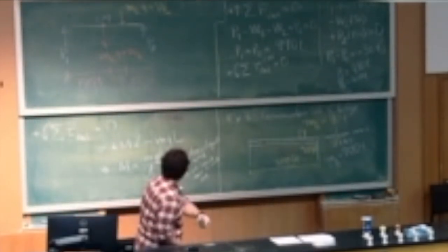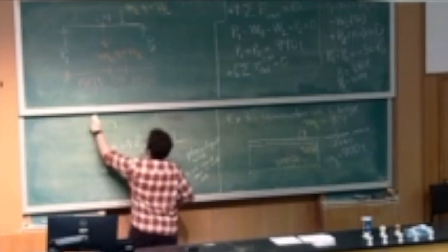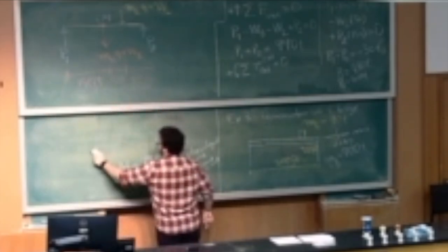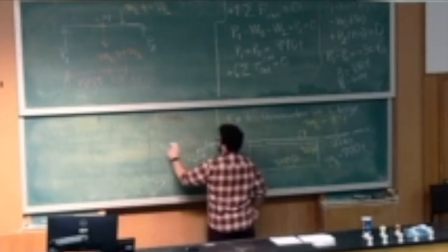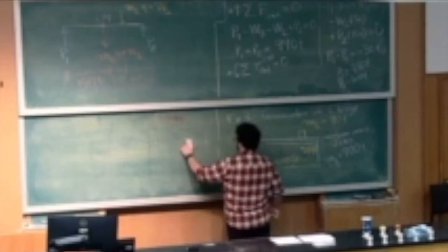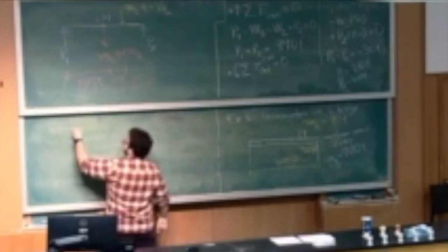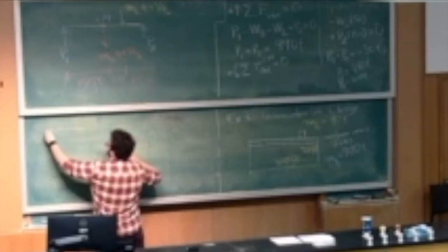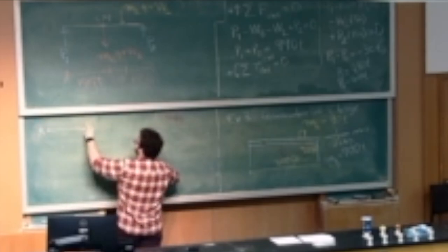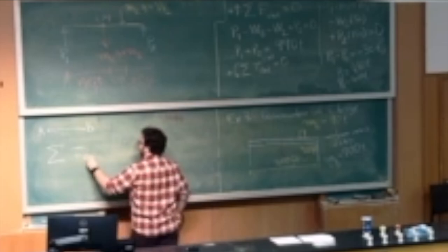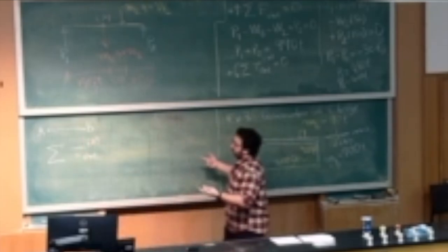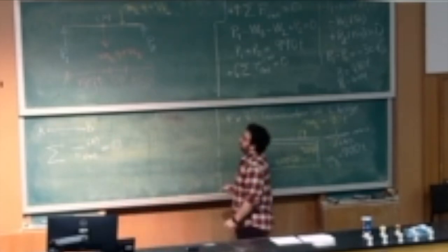So yes, this is a trick that we could consider. If you now just consider, say, one of the endpoints when you write down the torque equation, you will immediately eliminate one of the P terms, right? Okay, so this is what we mean. This is just a simplified figure for sake of notation. Let's call this point A, let's call this point B. If I write down all my torques about point A or B, I'm going to get rid of one of the forces already, and I will just have one equation that has one unknown in it, so I can solve it directly.